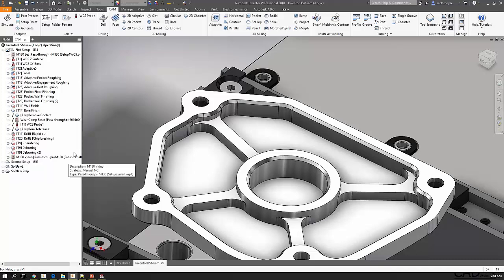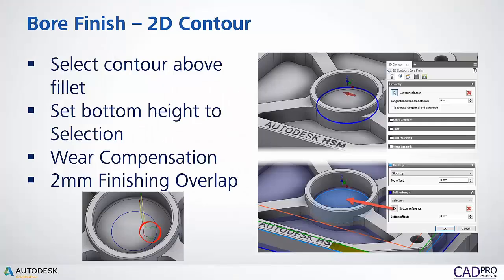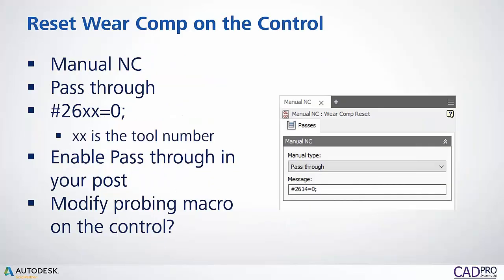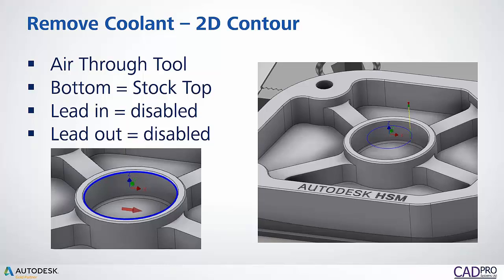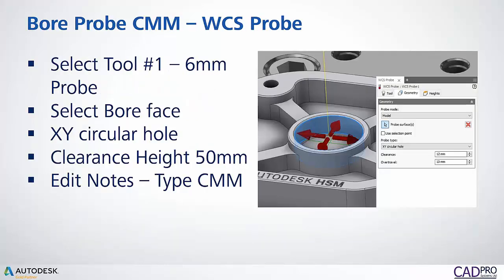So I've covered that. And there's a quick comment here that I think I'll address. It's from our intern Xander, and he's asking how do you respond to the question of how accurate the machine is at checking itself. I think it's good to clarify. Obviously, if the machine doesn't know what an inch is and it's out of calibration, then even probing is not going to help anything. What probing is going to catch is if the tool isn't cutting the size it needs to be because it's not in the holder perfectly, or it's cutting slightly undersized or slightly oversized, or if there's some deflection, you're going to capture that.